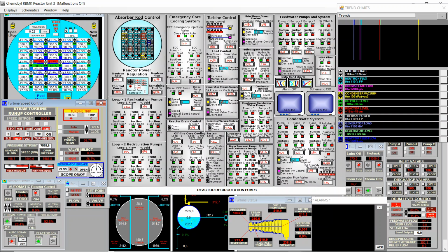We're at 30% of power set point. I don't start at 100% power set point because even a kindergarten kid can power down this reactor from 100% to 30%. So the tricky part starts when we go below 30%, that's why I start the video here. And we can also look at the thermal power slightly below 30, it's at 28.4%, and this yields almost 200 megawatts of generated load in the turbine generator.